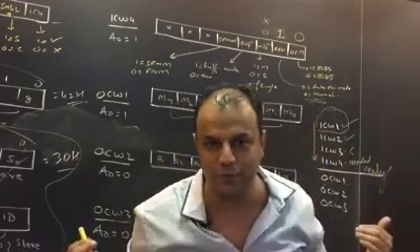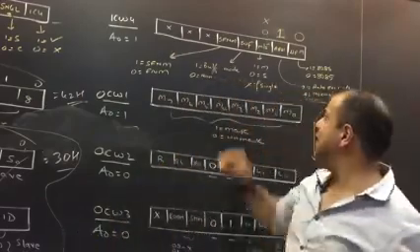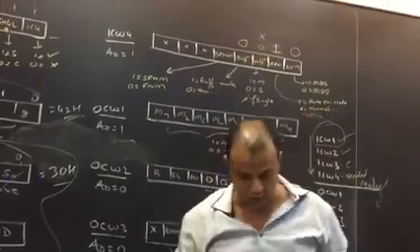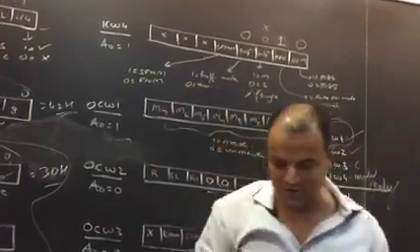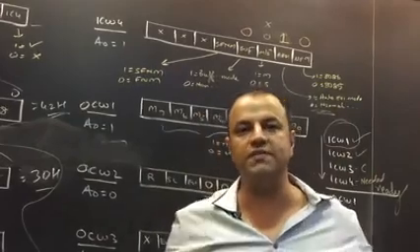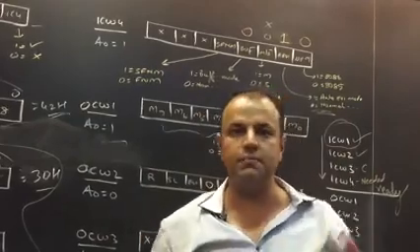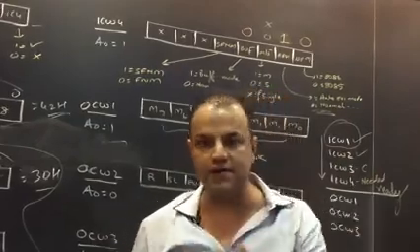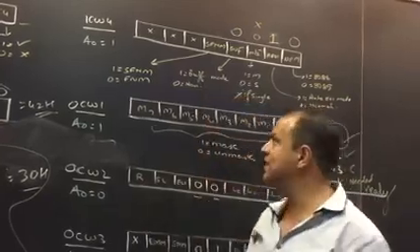Because 0 is the default option for everything. So being an 8085 programmer, for you this bit is always 0. Now sometimes examiners, just to irritate students, say buffered mode. If they say buffered mode, keep that bit 1. If they've said nothing, please keep that bit 0. 8085 circuits are not buffered. That option is there only in 8086.